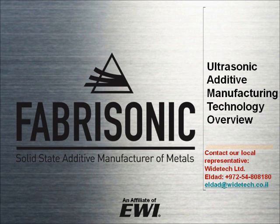As you can see, periodically we can come in with 3-axis CNC machining to add different geometry to the part. This can include internal passageways and external shapes. Layer by layer, you add material just where it's needed with very little waste to build up the three-dimensional part. The process is driven all by 3D CAD, so you take your CAD model and put it into the system and out comes a three-dimensional part.